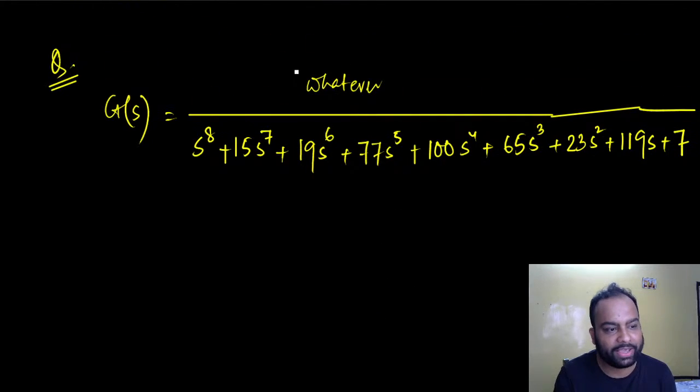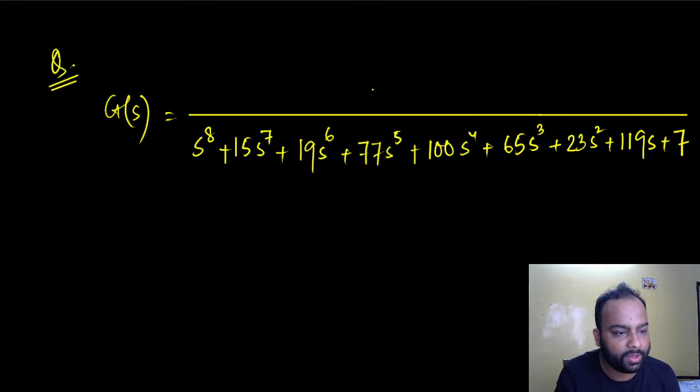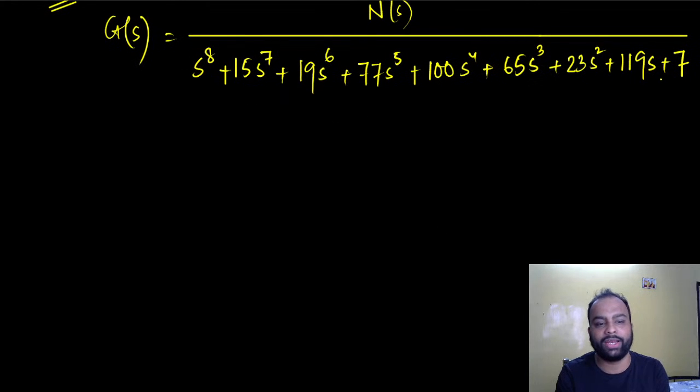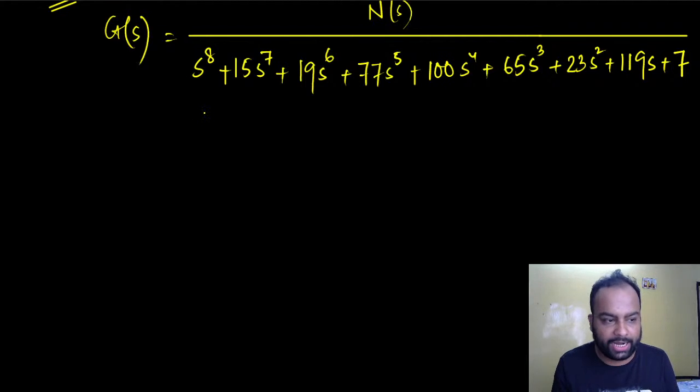Yes, if I give it to you in an exam, and if you're studying from home, so whatever, right? So I'd say numerator, polynomial, something like that. Okay, and if you are studying from home, of course you can just put it in Python, and Python will give you the answer, right? You will get all the 8 poles. If you write down this transfer function in Python and ask for the poles, it will give you all the poles, and by looking at all the poles, you can figure out whether the system is stable or not.